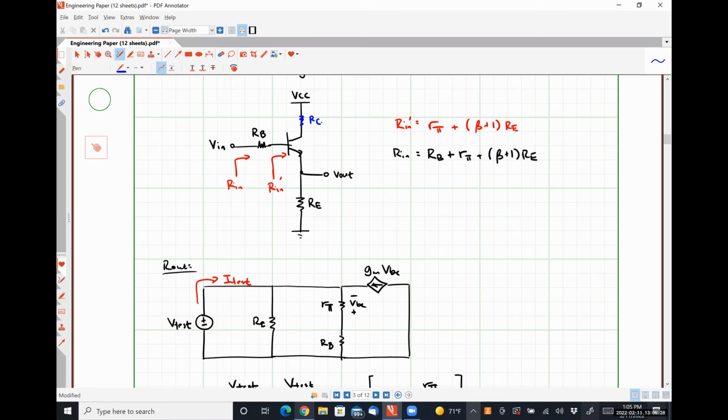It's not definitely a situation where we're going to have the device operating in the forward active region, because we don't have that feedback loop that literally forces that. But if it's operating in the forward active region, it's very deep in the forward active region, meaning we have a large value of VCE, and very likely we're going to see a large value of that early effect current that causes it to tilt up.